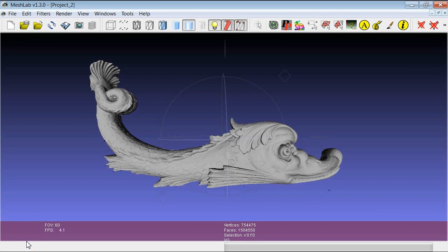In this first tutorial we will see the very basic operation of removing the part of the mesh or the points that you selected on a mesh. There are already a couple of tutorials about the selection, so we already saw some easy to use tools, but also some filters that give you the possibility to select peculiar parts of the geometry. And one of the most important things for which you use selection is selecting the part of the mesh that you want to remove.